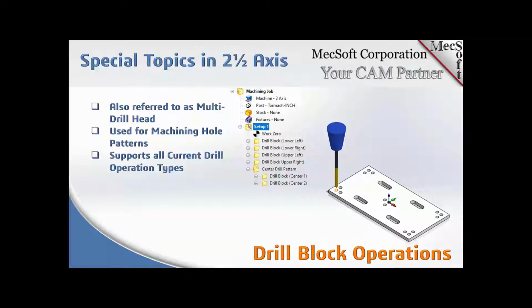Now, this is going to be a really interesting topic. If you're cutting a lot of holes in a production setting and a lot of hole patterns, you can get a drill block, which is also referred to as a multi-drill head, set to this pattern that you need to machine. And we're going to show you how to set that part up and use the multi-drill block to machine the part that you see here.